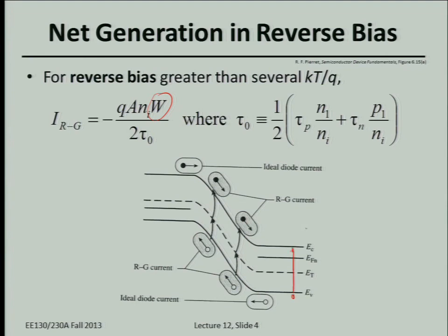They're just going to move around and eventually probably recombine. That's why we draw a Fermi level out here, because this quasi-neutral region of the PN junction is in thermal equilibrium. So there's not going to be any net generation or recombination. All the time you'll have generation, and all the time you'll have recombination.